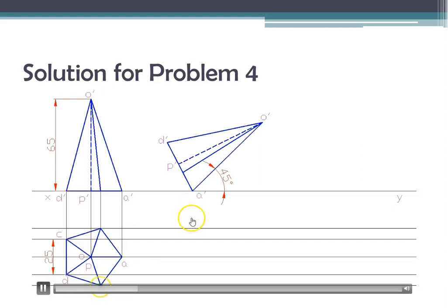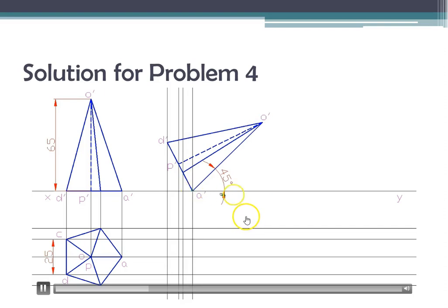And the lines are projected. And the corners and all the positions are projected, from the old top view and the new position front view. So where the corresponding points meet will be the next view. So this is done as usual.